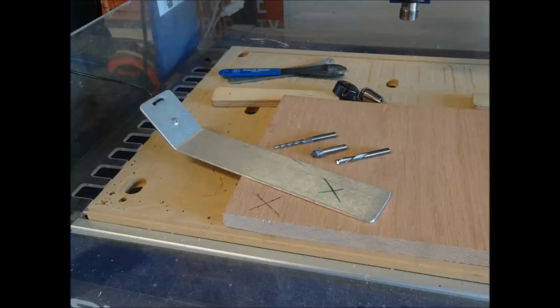And sometimes when you have, say, a pocket that has a prism toolpath or a clearance toolpath where you have to get multiple bits at the same depth, we have seen over time where you may get a line showing the difference in depth. Well, one way to get around that is by zeroing your bits in the same spot every time. There are things like material that are not always perfectly flat and parallel throughout.